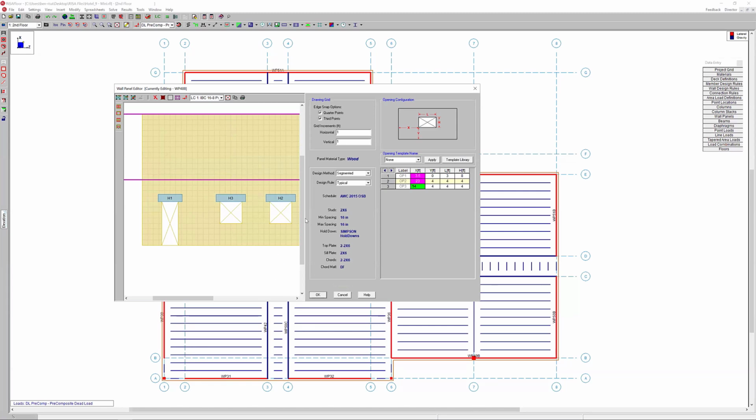The other thing I want to point towards is the management of warnings. If I add in, let's say, a 4th opening at 16, 4, 4, and 4, you can see right away that I'm getting an overlap. This is pretty obvious here, but I'm also getting red text highlighted, signifying that for opening 3 and opening 4 I have an overlap. That is an issue that will prohibit me from creating regions and ultimately from running the design.